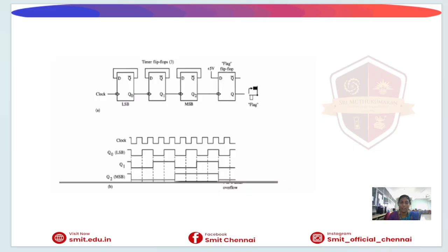The next one is the timer setup procedure. To use the timer, we follow these steps. First, load the initial value: a starting hexadecimal value is loaded into the TH and TL registers. Then start the timer by setting the TR bit in the TCON register.